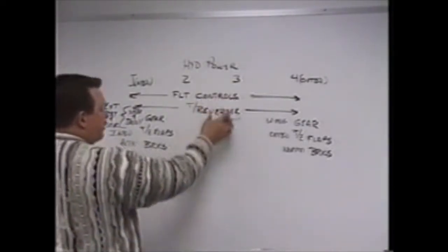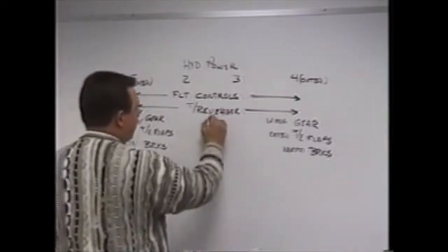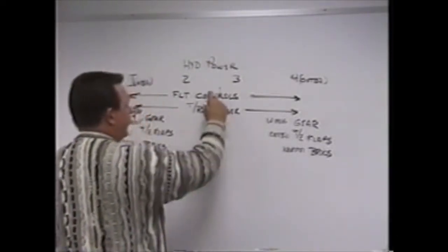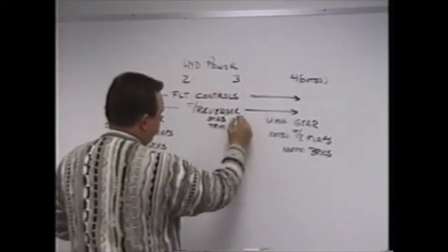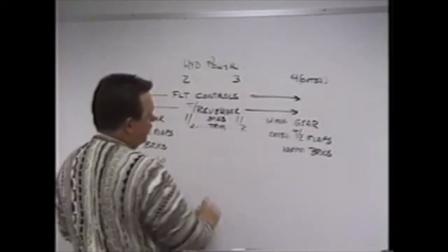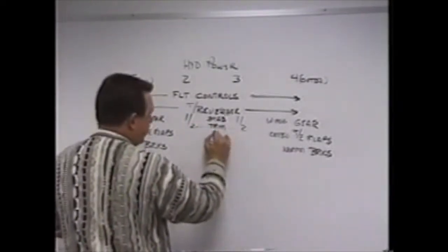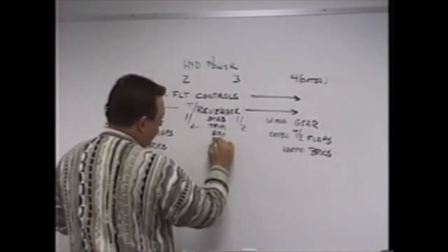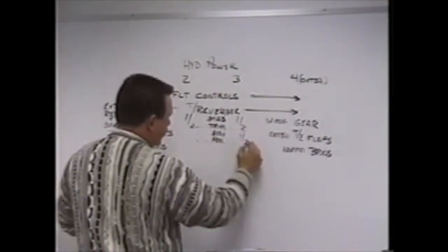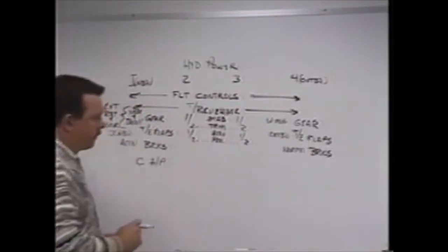In addition to flight controls and thrust reversers, we have stab trim. Stab trim is a flight control. We could put that up here under flight control, but we like to specifically point out that half of your operation comes off of System 2, the other half off of 3. Half of something else is your elevator feel computer, which takes hydraulic input from System 2 and System 3.